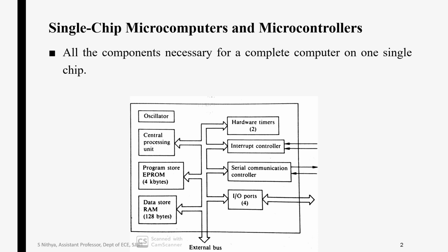A microcontroller is similarly a single chip device that is specifically designed for embedded computer control applications. The main difference between the microcontroller and the microcomputer is that the microcontroller typically has an on-board multiplexed ADC and some form of processor outputs. This chip may also contain a real-time clock generator and a watchdog timer. That is the difference between the microcontroller and the microprocessor.